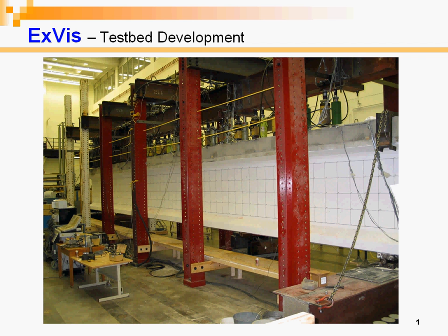The ExVis program was developed using a test bed of data collected from 20 load tests on large pre-stressed concrete girders that were conducted as part of a project sponsored through the U.S. National Cooperative Highway Research Program. Each of these girders was 6 foot deep, simply supported over a 50-foot span, and subjected to a uniformly distributed load using 44 hydraulic jacks.